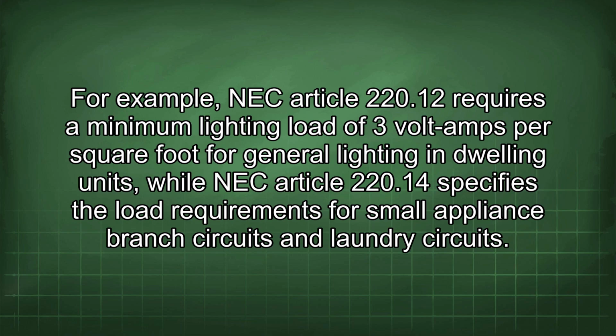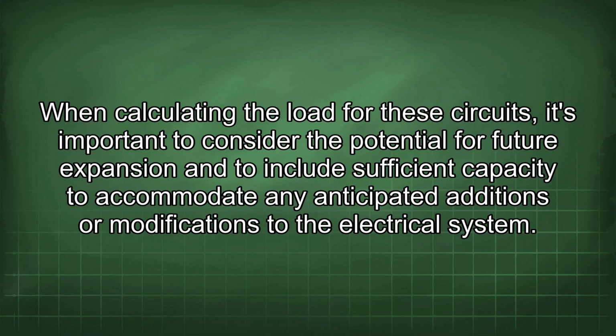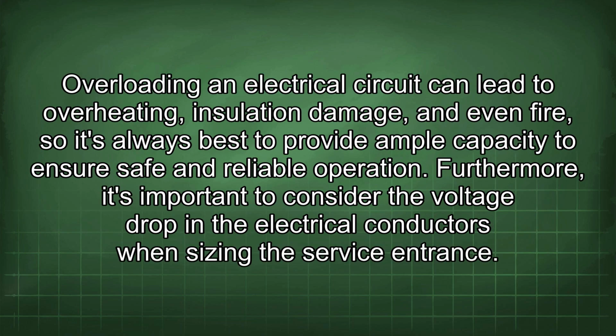laundry circuits. When calculating the load for these circuits, it's important to consider the potential for future expansion and to include sufficient capacity to accommodate any anticipated additions or modifications to the electrical system. Overloading an electrical circuit can lead to overheating, insulation damage, and even fire, so it's always best to provide ample capacity to ensure safe and reliable operation.